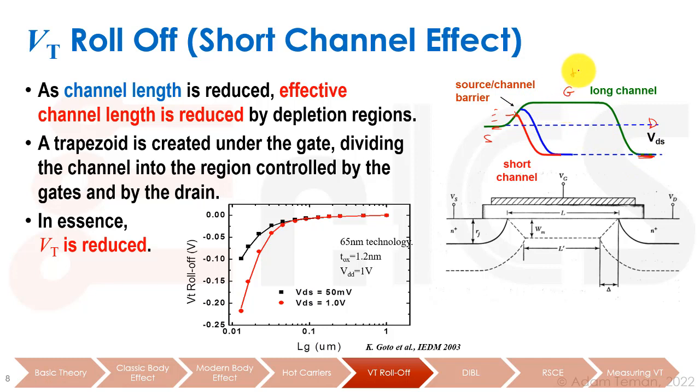And what happens is when we put some voltage on the gate, the energy level of the gate barrier goes down, and when it gets down low enough, then these electrons can fly over. So we want to have this barrier high, and then be able to put some charge or some voltage on the gate to move it down until it's low.